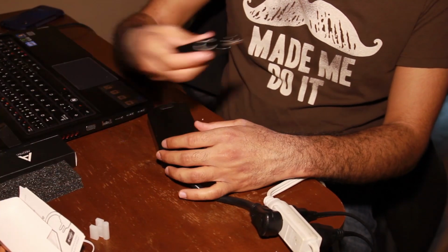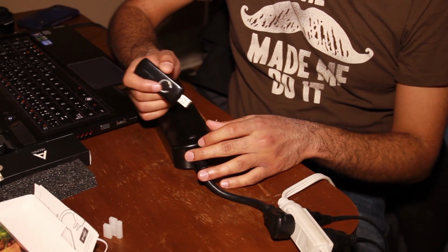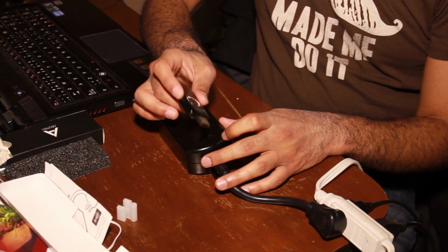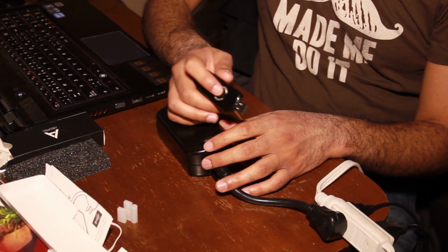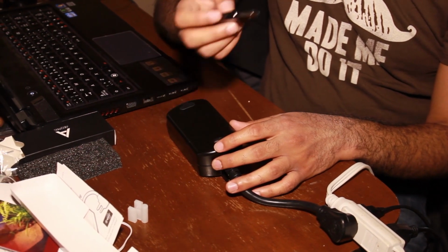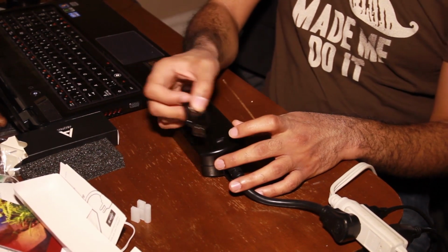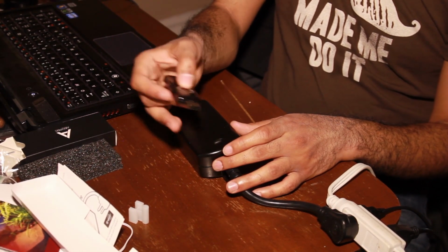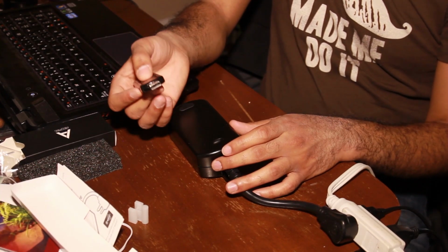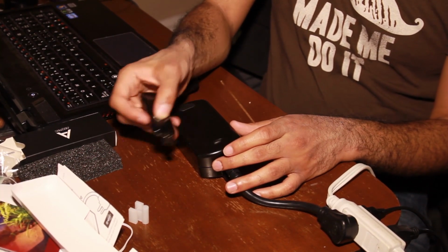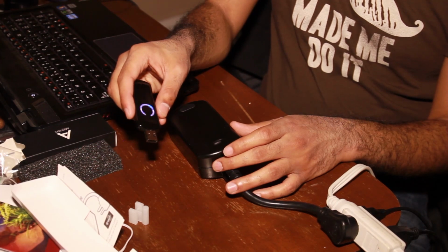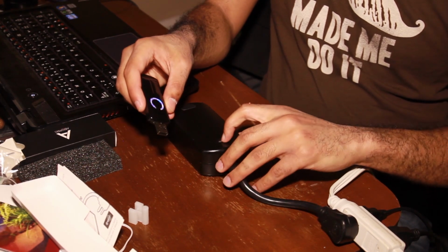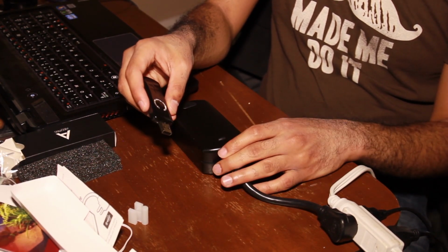And if I take the Z-Stick from before, this is actually a really cool stick because it comes with a small battery, and it also has the ability to include devices. The way Z-Wave inclusion works is you pair devices together like Bluetooth, except they have to be within, I think, about 3 feet of each other, because you don't want your neighbor pairing their device with yours. So you press this button once and it starts to blink slowly, and then you press this button and the blue one should go solid, but I think since I've already paired this, it's not going to do that again.